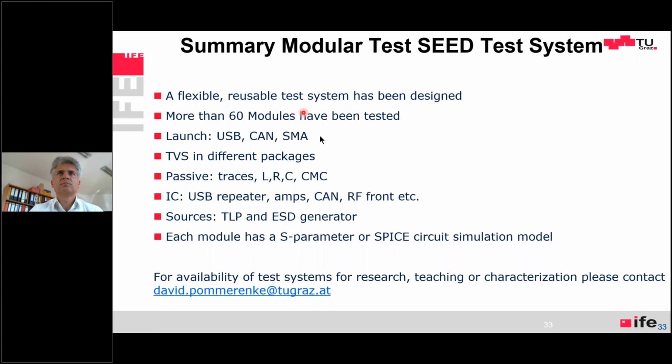You mentioned a TLP. Can you explain in more detail what that is? Yes, a TLP is the most simple thing you can think of in the world. Think about, you take a coax cable, and you charge up the cable, the shield to the inner conductor. And then you have another cable here, and you connect the inner conductor with a relay. Click, you close the relay, and this relay is closed in picoseconds.